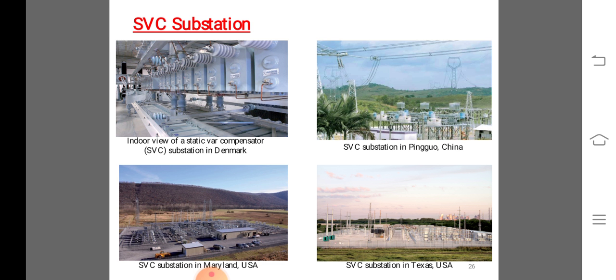Then commutation from capacitor to reactor and vice versa should be fast. No switching of the capacitor at the high voltage bus bar, so that no higher frequency transient is produced at EHV level. Elimination of higher harmonics on the secondary side and blocking them from entering the system.